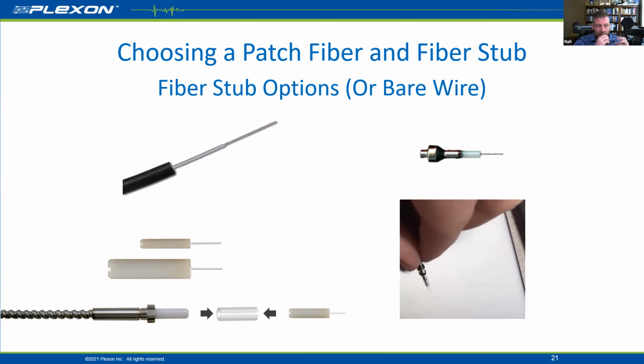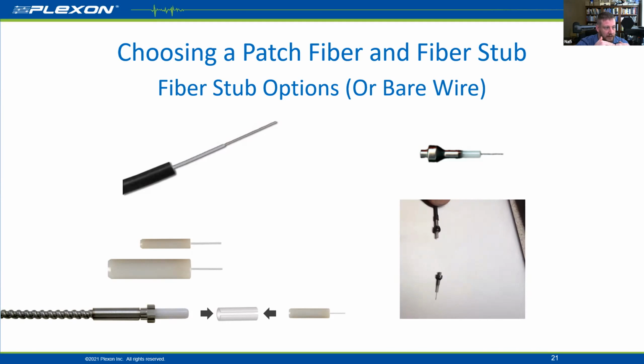Normally, the advantage of the FC connectors and the LC connectors is they perfectly align the cores with the center so that you're gathering as much light as possible. So if you're having this double core side by side, you're going to end up with some power loss. If, at the end, you're measuring the power coming out and it's enough power, then it's not a problem, but just something to consider.